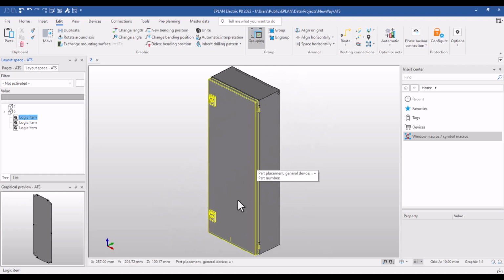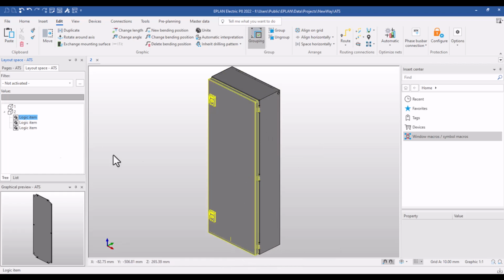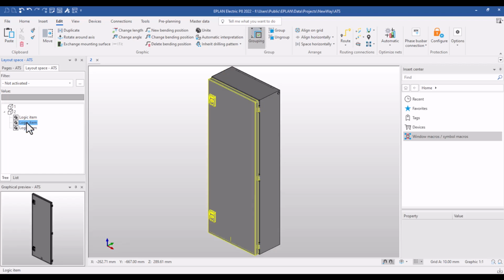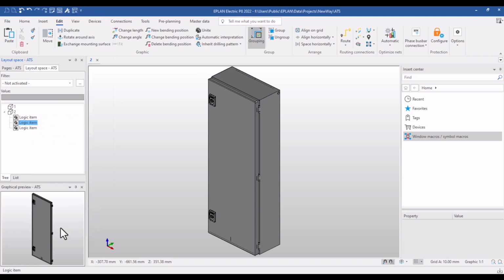Okay, like that. You can see the entire isometric like that. Okay. What I need now is to define each part of these enclosures, starting from the mounting panel, the door, and the body. To do so, we will first go to the door to define it. To define this door, we will need to define it by properties. We will right click and go to properties.